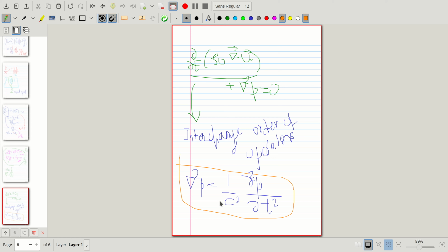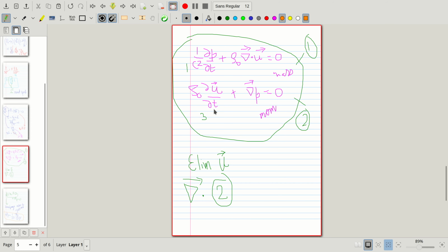In fact, for particle velocity we had to use the pressure gradient. If you were wondering why I had to do a pressure gradient, let's go back to this equation. You see the acceleration of the particle dou u by dou t is related to the pressure gradient, right? So if I look at it as a finite difference approximation, the dou p by dou x is nothing but delta p by delta x.